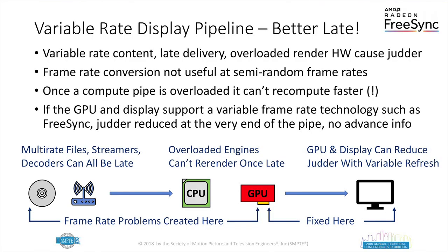What you do have available is just what's in this back end of the pipe, and that's the display portion of the GPU. That's not doing any fancy compute. That's just picking rendered images from the frame buffer, throwing them to the display, and you've got the monitor, which if you start reprogramming the firmware and recalibrating it, you can do a lot of variable frame rate work. So that's the world we're working in. Slightly inadequate hardware for what people may have intended to do. By the time you get here, it's too late to fix it. And what you've got left is, can I make the monitor synchronize to the frame rate I've got, frame by frame, so that I'm not doing drop repeat frame rate conversion?